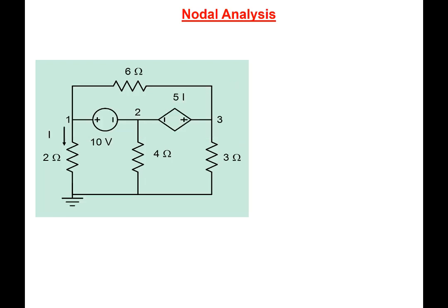We could have done this problem in an alternative way. In a circuit like this, we were given this node as a ground. But note that it's only a reference. Even though it's written ground here, we can choose the reference any way we want during the analysis, right? So these are all the 4 nodes here. Temporarily we can forget about this ground node here, and we can choose whichever node we want as reference, as 0.